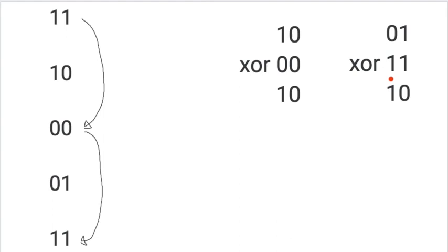Now the same is true for counterclockwise. When we rotate counterclockwise, it goes from, say, 0, 0 to 1, 1. Okay? 1, 0 XORed with 1, 1, well, that's 1, 0. And the same is true for here. And now we can see the pattern. With the counterclockwise having a constant and the clockwise having a constant, if we XOR the final detente and the intermediate together, we'll get one of the two, we reference it, and there we go. We have figured out which way the encoder is turning.